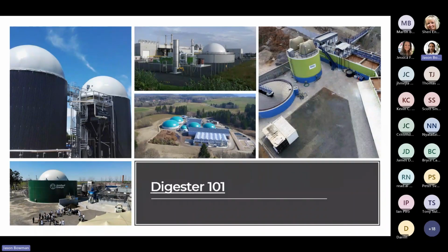That is, you might have a digester with 1 kilogram per cubic meter loading rate and others above 10. So there's just a wide variance, and that's because of the waste source or the feed source going into these digesters. So the purpose of this slide is just to give a good visual representation of various digester configurations and project models. So we have here ranging from small holistic systems aimed at really more of a wastewater or localized treatment system to larger biogas powerhouses that are generating a lot of energy and create recurring revenue for the operator, for the end user.